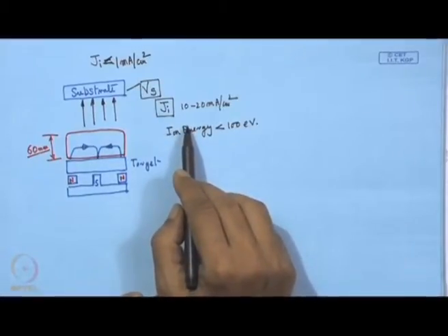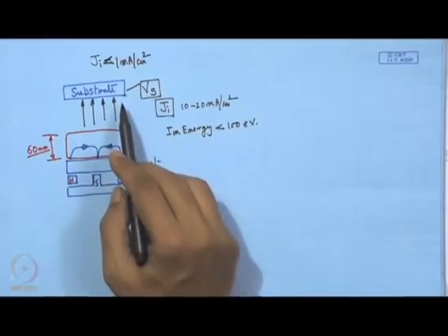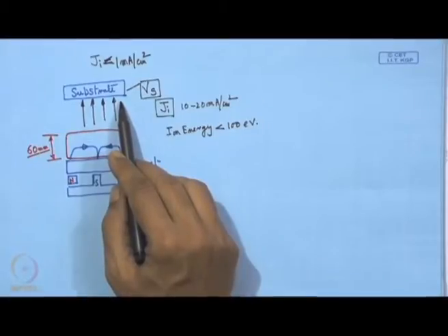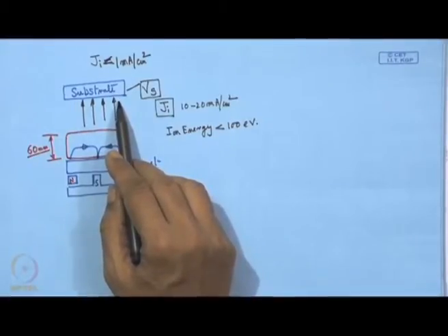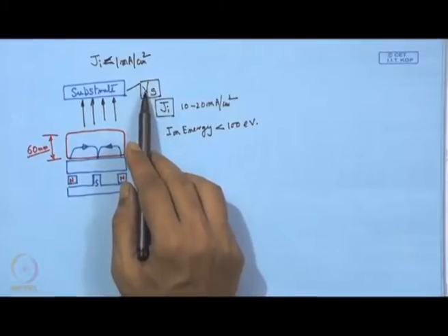If we can have such a situation, then we may expect a well adherent, well dense coating without too much surface defect and residual intrinsic stress, which may be the result of high substrate voltage.